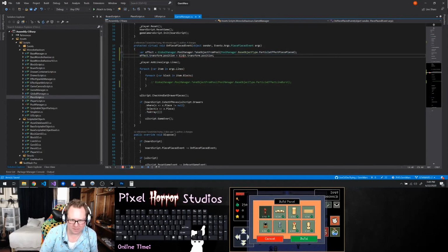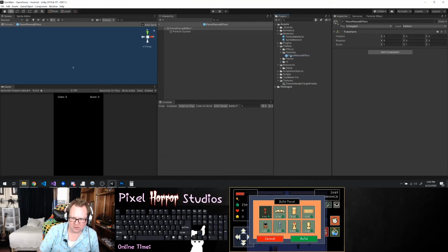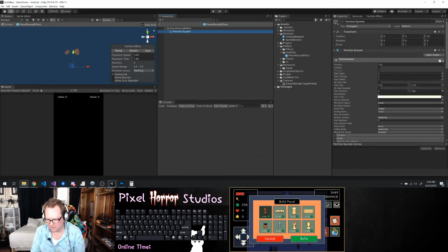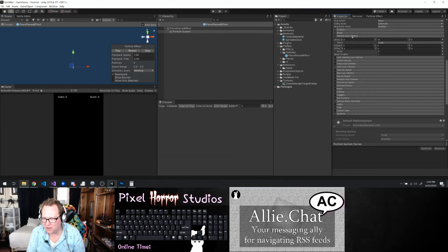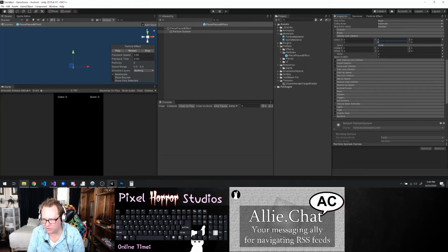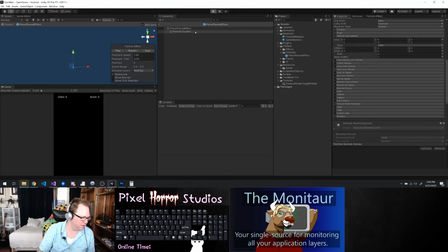I only want to put this at my args.piece_place.transform. And that means I can up this effect to have a max particle size of 20. 16. My velocity over the lifetime, we want to do a constant between 8 and 12. Let's give that a try.